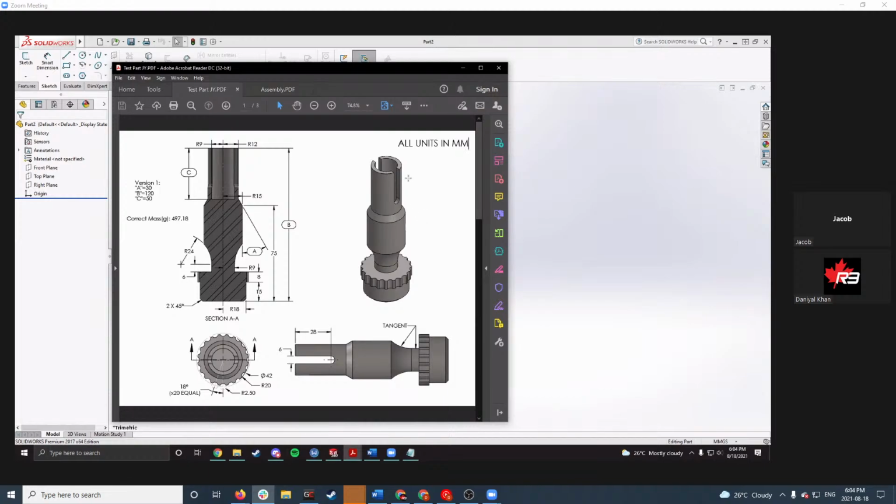Because this part is cylindrical in shape, my thought process is to draw the profile of the part, specifically half of the part, and then revolve that in a circle to make the entire cylindrical portion. This cross section has all the important dimensions and all of our global variables that we'll be using. I'll touch more on that a bit later.